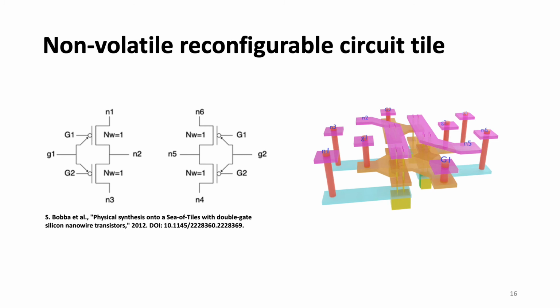While the previous slide showed the usage of this kind of device in routing applications, it is also desirable to consider its application to logic and data processing resources. Work some years ago at EPFL on ambipolar lateral silicon nanowire FETs resulted in a generic reconfigurable tile architecture where the various inter-device connections define the actual tile functionality. In this work, we use the non-volatile properties of our technology to make this tile reprogrammable.